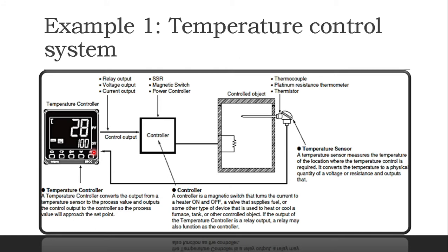If there is a difference between the programmed temperature and the actual temperature, it generates some error, and then the controller sends a signal to the heater. Through the interface it sends the signal to the heater, which is amplified and, using a relay, brings the furnace temperature to the desired value.